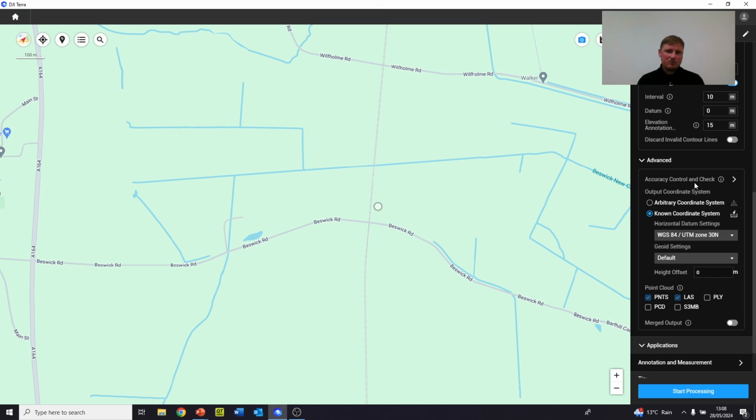So with DJI Terra, when it comes to the LiDAR processing, you might want to do something differently. For example, I use highly reflective targets, so I can see them in the intensity values and select that center. But one thing to remember is that when DJI Terra is utilizing these points, it is merely a check. It's not adjusting that data to the points at all. It's for you, who is processing that data, to validate that data and make sure it's within the specification you're working to. And typically, at, say, 55 meters, we'll be looking for an XYZ of around 50 mil.